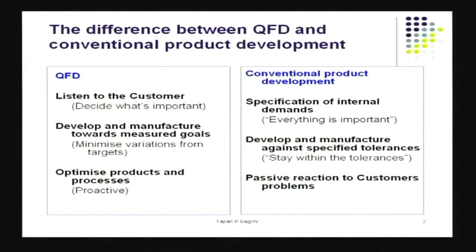Let's look at the conventional approach to designing a product. You start with what we call specification. So if it's like a pen, what are the specifications of a pen? First of all, let's look at the two parts. We got the cap. The cap has a clip. And if you look a little closer, the clip has a little tolerance there, so some numbers will have to be given. There's a length of that clip. Then you come to the top of it, there is a certain curvature that perhaps gives it some aesthetics. Then you look inside, there's a hole there, and the body has to go in there. And that fit has to be airtight so that the ink doesn't dry out when the cap is on.